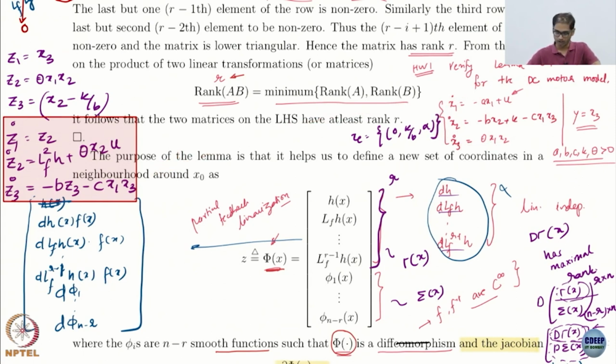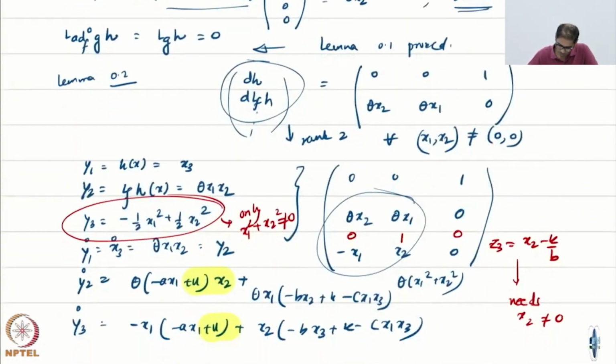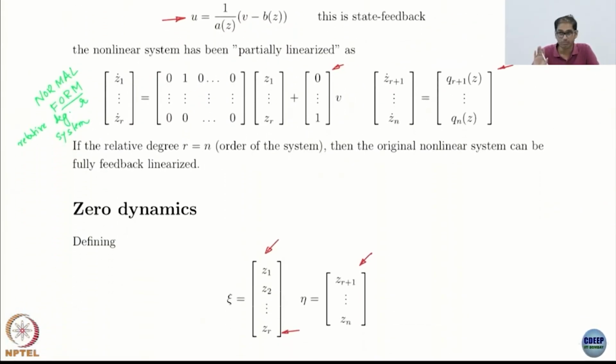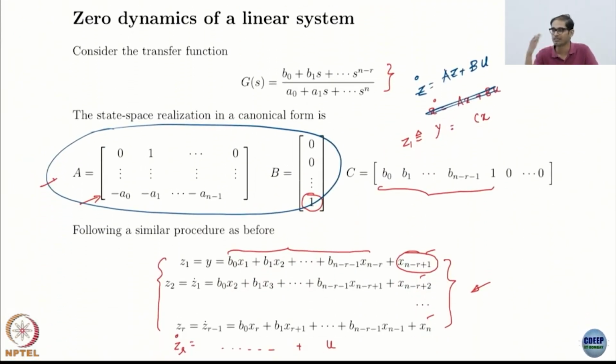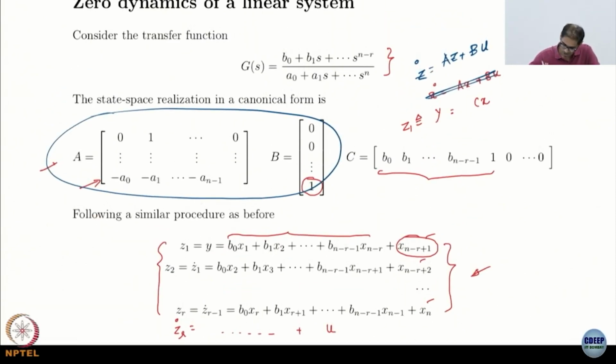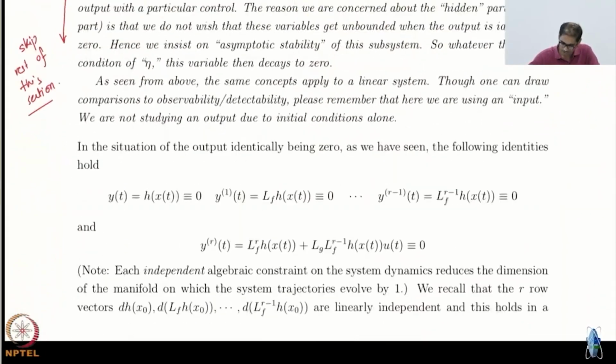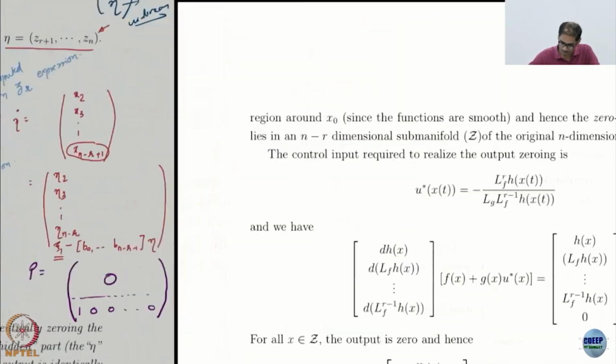All right, folks. So feedback linearization is relatively powerful, because you are doing a state transformation by using some method. It almost looks like some bunch of magic potions or incantations, right? I did some LgH, LfH and a bunch of LgLfH and LfLgH and so on, and I reach some fun place where I can get some nicer looking system. Quite powerful actually. There is good logic to why it works, but it's still quite powerful.